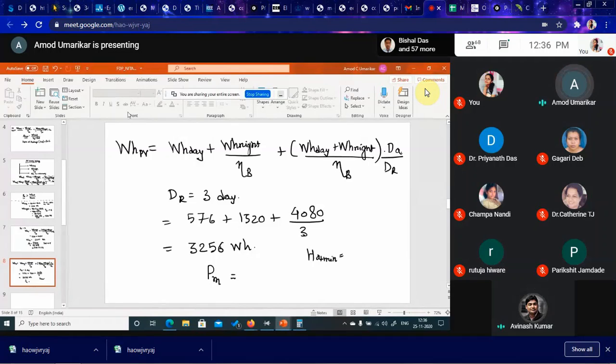The average insolation is about 4.5 kilowatt hour for 1 day of generation for 1 kilowatt. We are considering this for the Indian scenario, about 4.5 kilowatt hour for 1 day of generation for a 1 kilowatt power plant. I'm just seeing what the actual load calculation is, and based on that I am sizing this.